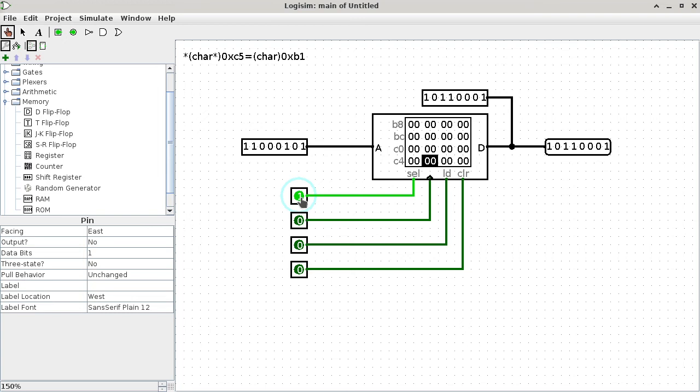That's because of the clock. The RAM component, just like the edge sensitive D flip flop, is edge sensitive. That means the clock has to transition from 0 to 1, and right at that moment of transition, it will take whatever is from the D port to update its internal content. Is that okay? Yep. This is only applicable if we're trying to write in memory, right? That is correct. So read does not require an edge whatsoever, but write does. Okay, that's a very good question.